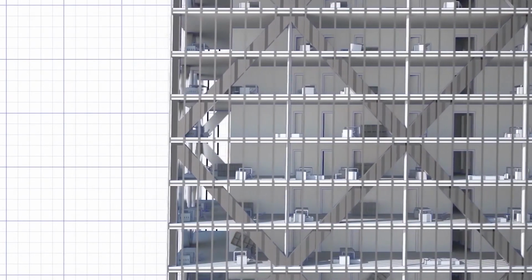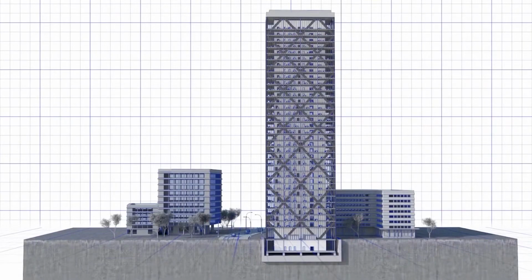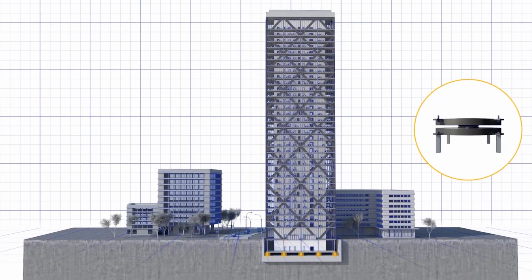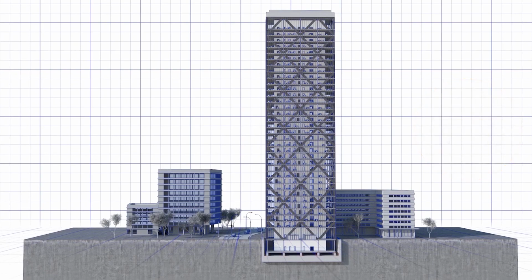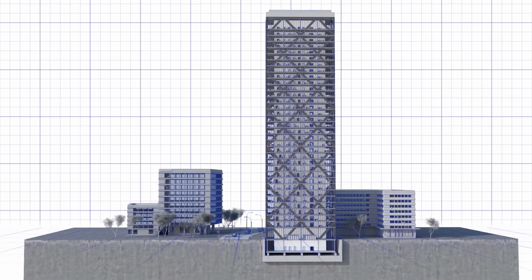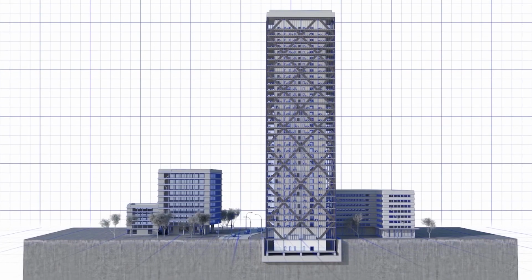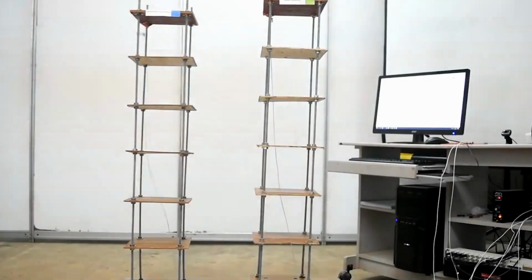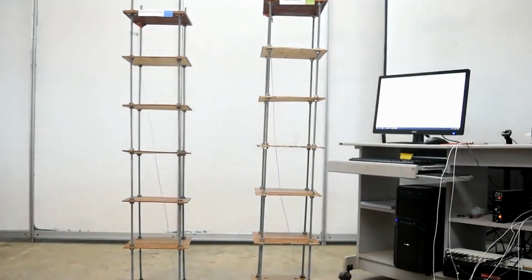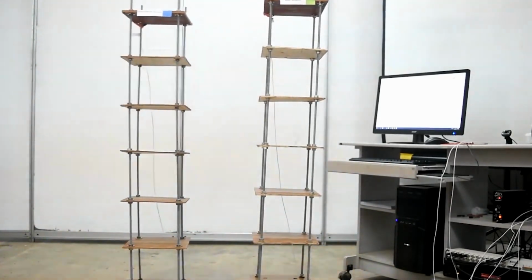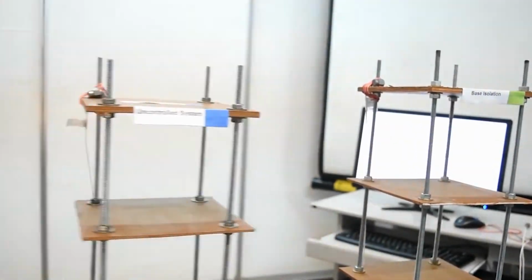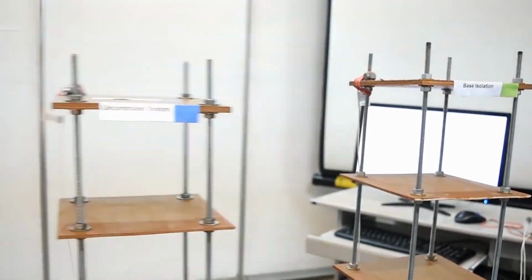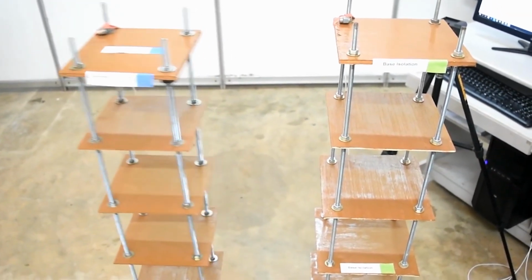What must be the measures taken by us? Seismic dampers or shock absorbers absorb vibration by dissipating the energy of seismic waves. Primarily, high-rise structures use a grid of steel beams and columns to distribute seismic forces evenly, along with diagonal shock absorbers. In our department, we have shaking tables to simulate the ground motions that take place during an earthquake. Design standards must be carefully determined by foreseeing the magnitude of earthquake for the region where the infrastructure is located. Moreover, construction techniques and monitoring principles should add more value to the structural aspects.